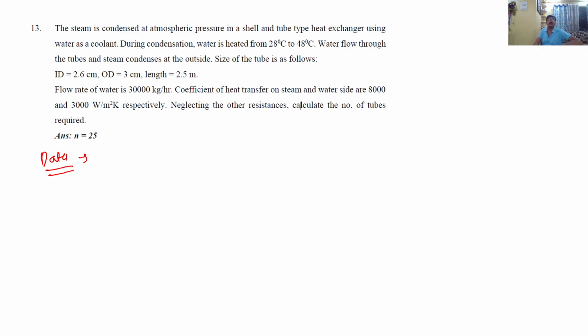Our first job is to identify the type of heat exchanger. Is it parallel? Is it counter? Is it condenser or is it evaporator? The steam is condensed, so the very first sentence tells you this problem belongs to a condenser. So start drawing the diagram of temperature profile.